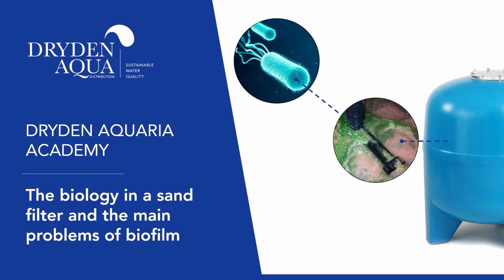Yeah, and not only sand filters, just mechanical filtration. So you also get that with some of the other medias as well. For instance, if you're using zeolite media, you'll have big biological problems as well. So it's not only sand, but sand, I would say, is the most used around the world. Or in a filter, even our own, that is incorrectly managed. If you don't backwash it properly, you will leave organic material in the filter, and therefore a culture will start. And that's what you want to avoid.